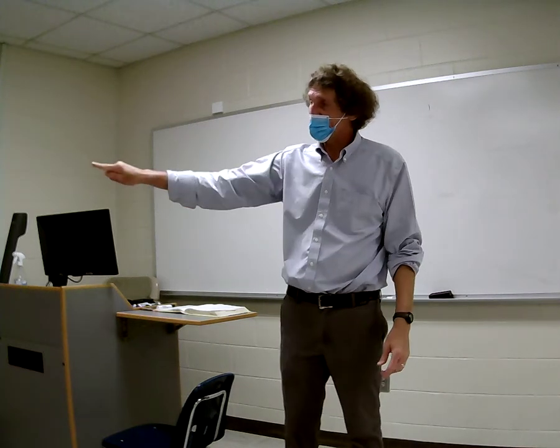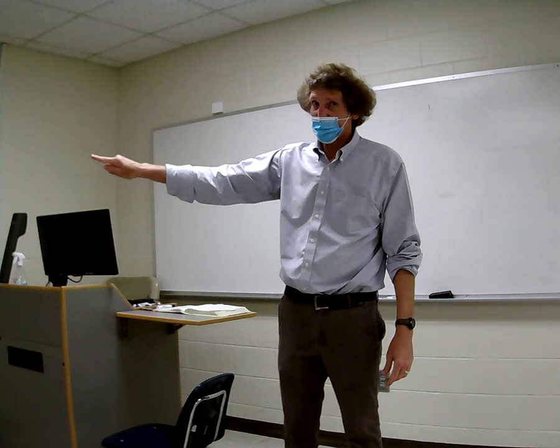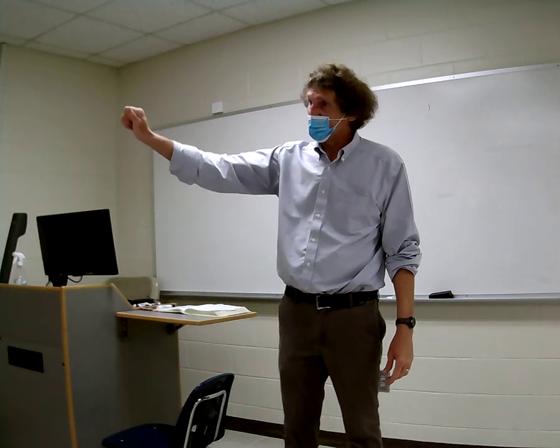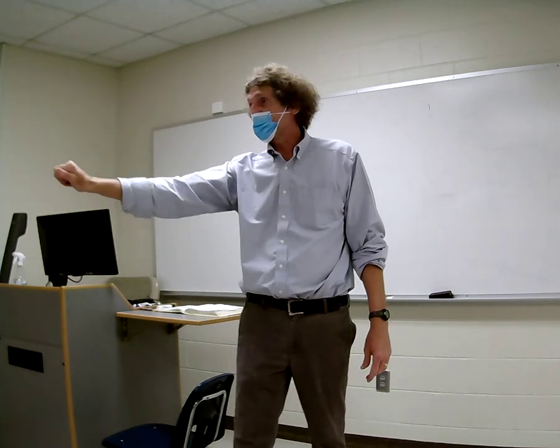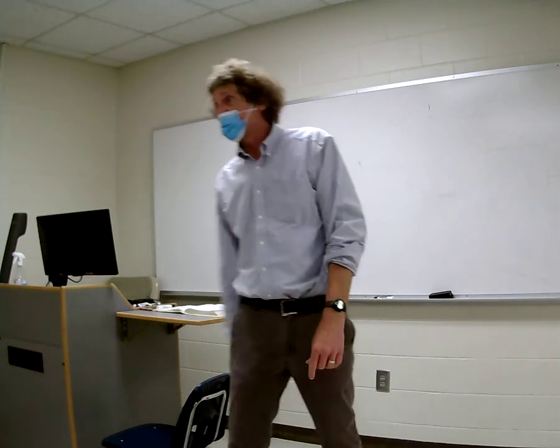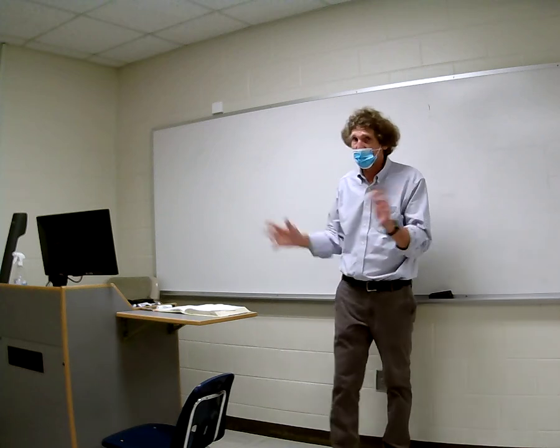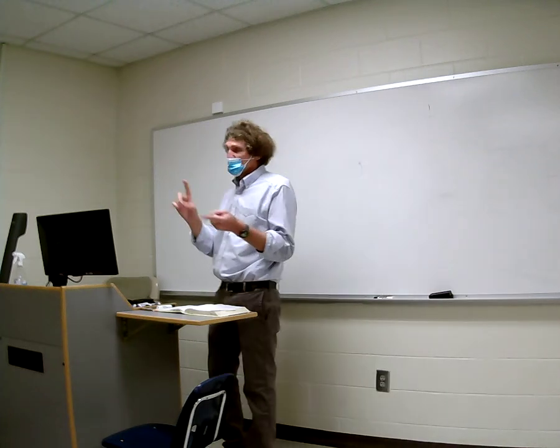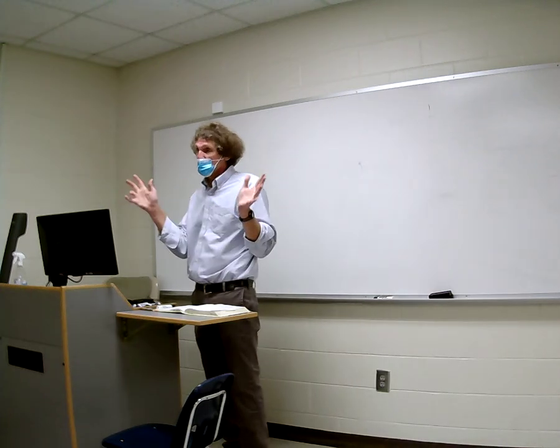If you have a safety ground on your system, it's that green wire. If I'm holding this and the floor is earth ground, and for whatever reason something broke off and I'm touching the hot line, it won't go through me. Actually, you couldn't touch the hot line directly, but you would have the thing short through the internal ground. There's more to this, but that's basically what a ground is for: safety, and for measurement, for ease of use.